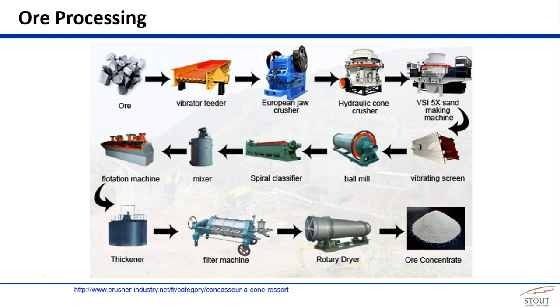Because the silica and certain other carbonate compounds are more water-loving than the metal oxides themselves, if you've crushed the mineral and mix it with a proprietary surfactant, a special soap, you can make the more water-loving ore, the gangue, sink to the bottom, and the metal-rich particles will ride air bubbles to the top of a flotation cell.